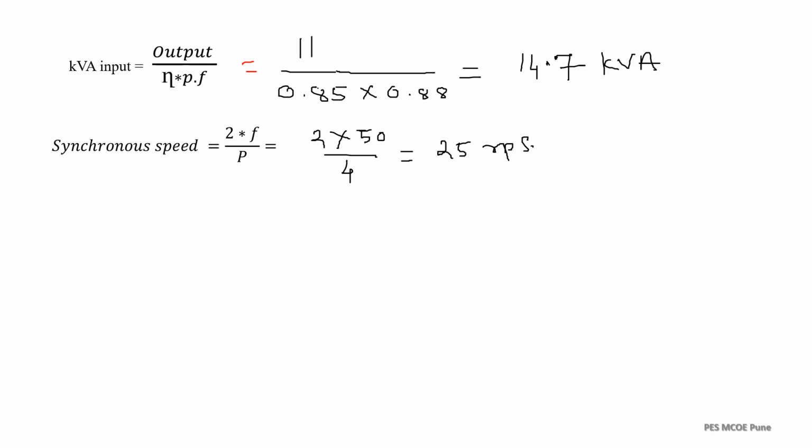Okay, so next we need to define winding factor, that is kWs. If they have given, you can take the given value directly. If not, we can assume this value approximately 0.955. Okay, so this value we have assumed.